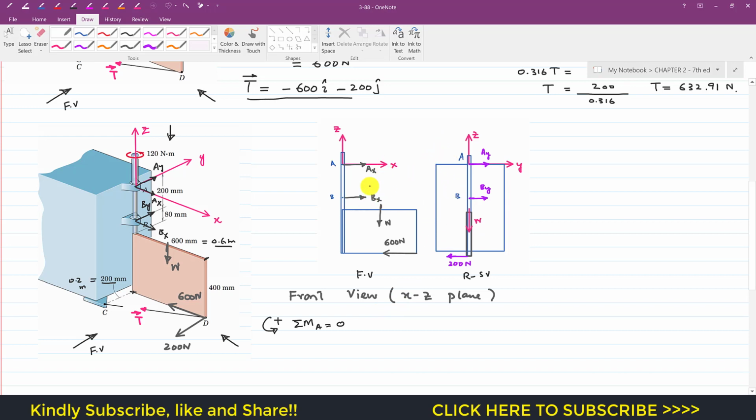Now as we can see, this Bx is going to produce a counterclockwise moment, so I will write plus Bx, and the perpendicular distance of this Bx from point A is this distance, which from here we can say is 200 mm, which is 0.2 meters. The distance between A and B is 0.2, so I have to multiply this with 0.2. This is the perpendicular distance, or we can say the moment arm of this Bx.